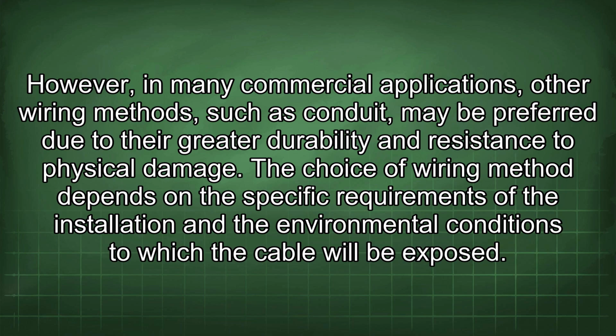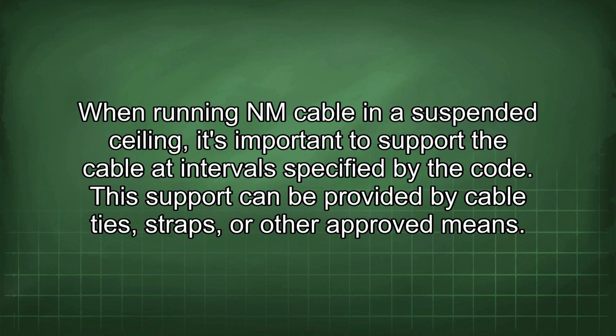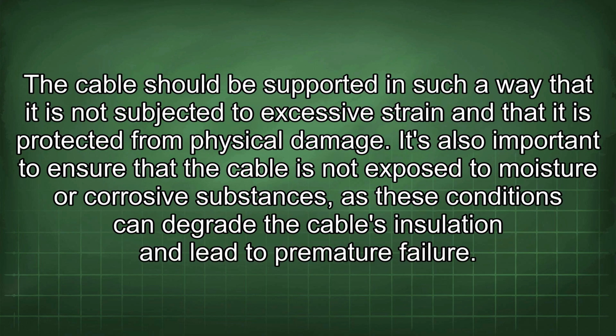When running NM cable in a suspended ceiling, it's important to support the cable at intervals specified by the code. This support can be provided by cable ties, straps, or other approved means. The cable should be supported in such a way that it is not subjected to excessive strain and that it is protected from physical damage. It's also important to ensure that the cable is not exposed to moisture or corrosive substances, as these conditions can degrade the cable's insulation and lead to premature failure.